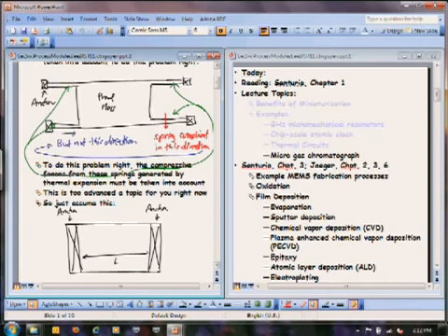Yes? So in practice, the presence of the beams has... Well, actually, no. It may increase buckling, but the buckling will be in the beams instead of the proof mass. Because it's now a longer structure, which means that the difference in thermal expansion between the substrate and the structure could be bigger in this case. These are also thinner beams here, so you may have a worse problem.